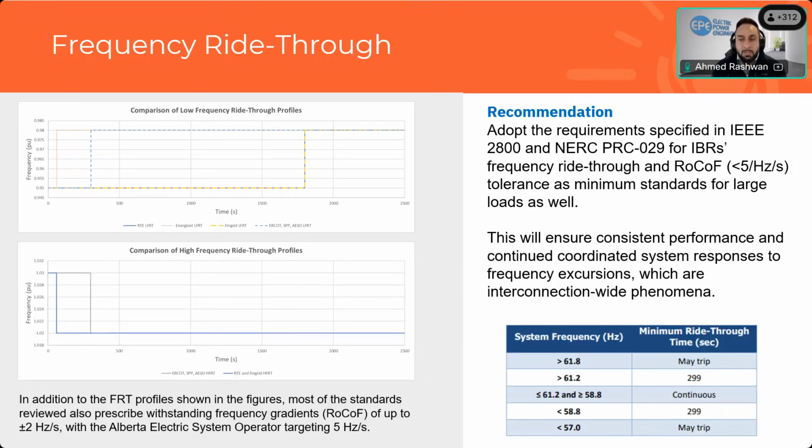And so as we looked into this, we noted that it's prudent for us to look into having these large loads meet the requirements specified in NERC PRC 29 for IBRs. And that includes ride-through curves as well as tolerance for rate of change of frequency. So this is an alignment with what we see with other electronic-based facilities. We felt it would also be good to align on those for frequency ride-through.